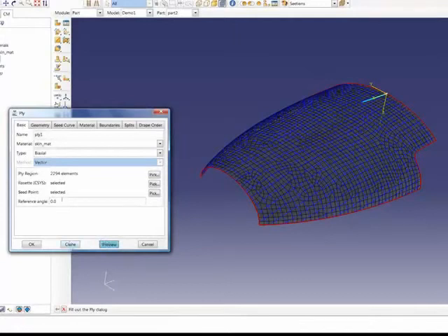And we're using a 0-degree angle to show our plies, and to do a preview you can see the fibre angles. Changing this to 45, you can see the result there, resulting fibre angles in blue, and in red is the ply extents covering the whole of the surfaces.